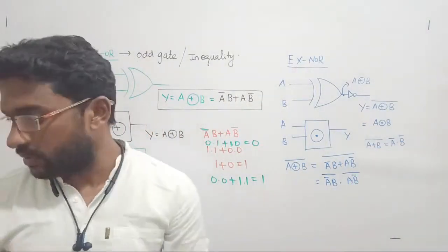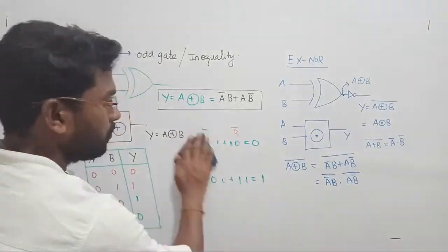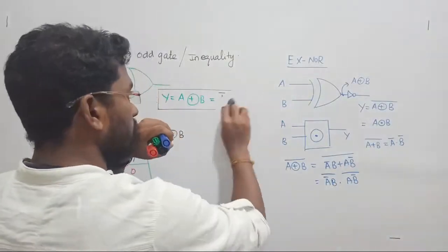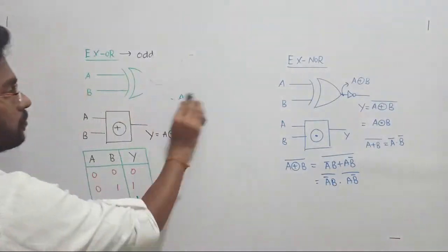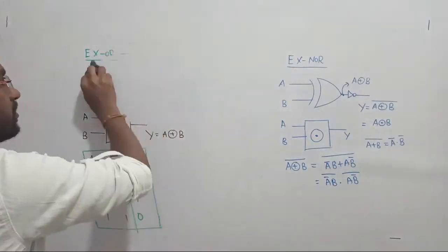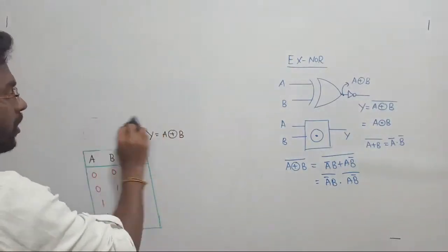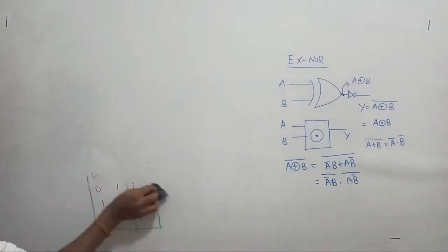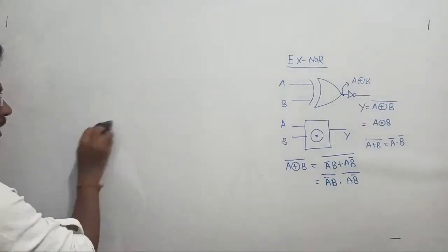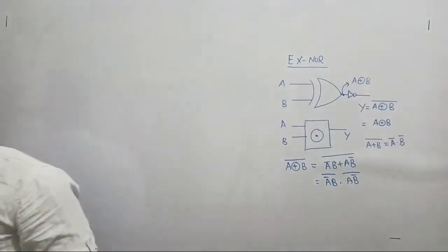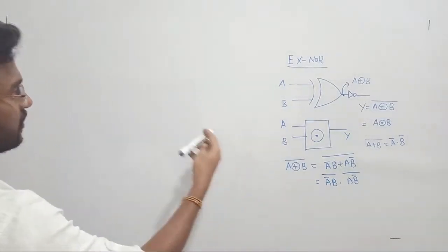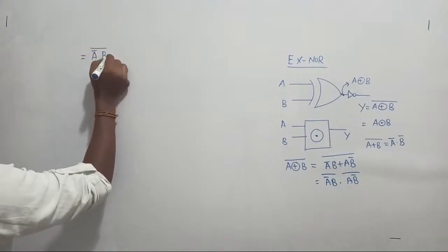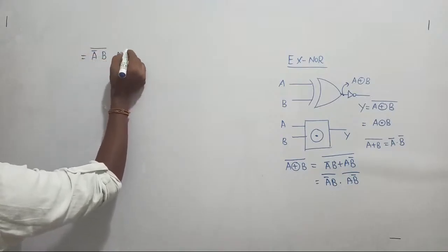But let us reduce this function further. So let me rub these things now. Slowly we will realize all those things, right? Let us continue. I'll apply De Morgan's law. Once again, if I apply De Morgan's law for this function, what we are getting, actually, is a bar dot b whole bar dot a dot b bar whole bar.